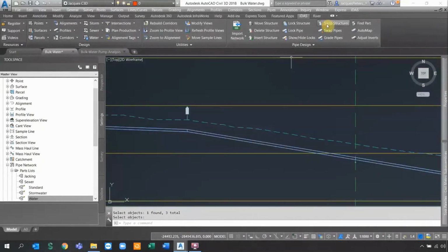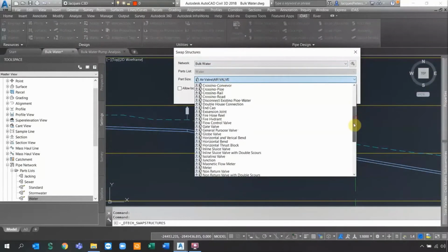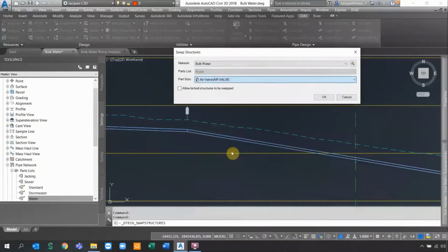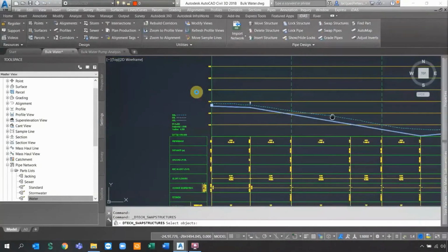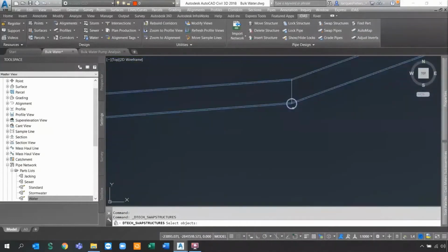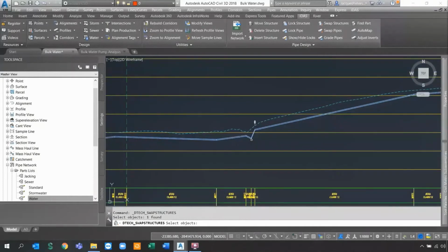In long section and in plan view. Then for the scour valves, let's add a few scour valves so you can get a feel of what type of elements we've got inside of our templates. If I go to the scour valves, I can specify exactly where my low points are. I'm going to put that one as a pump later on. So let me select one of these and select another low point somewhere over here.